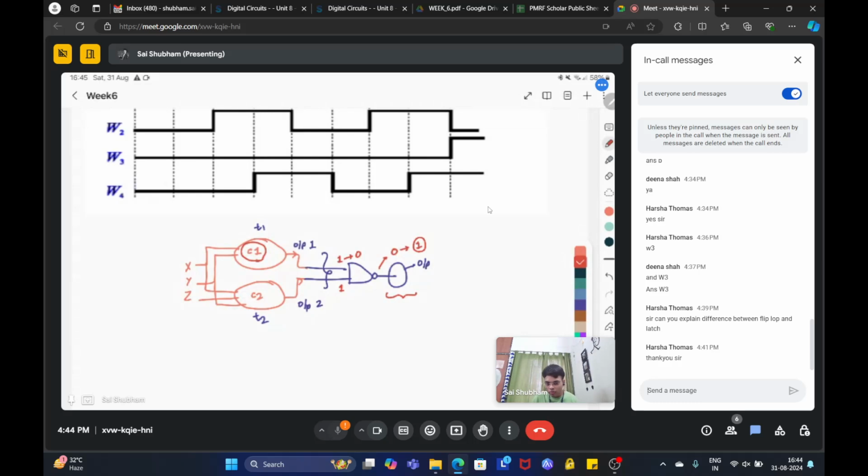This will create problems, because you do not know what your exact output is. This actually causes problems in time sensitive circuits, for example processors, or in hazard circuits such as an emergency alarm. You do not want your output to be continuously dependent on your inputs. Okay. So in that case, you need a flop instead of a latch. I hope this is clear.